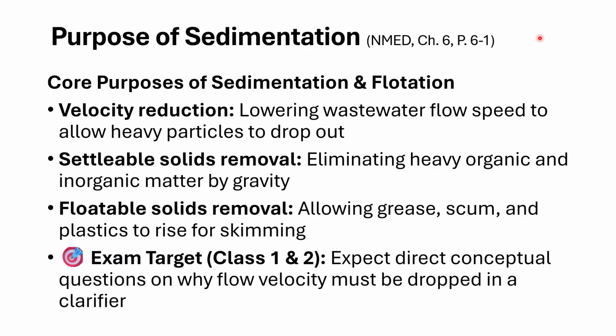And when that hits the preliminary or pre-treatment phase with the bar screens and what have you, we're slowing that wastewater down from 2 feet per second to 1 foot per second, to go through the bar screens, the comminutor, and the grit washing or grit removal system. And then when we hit the primary clarifier, we're significantly reducing that.